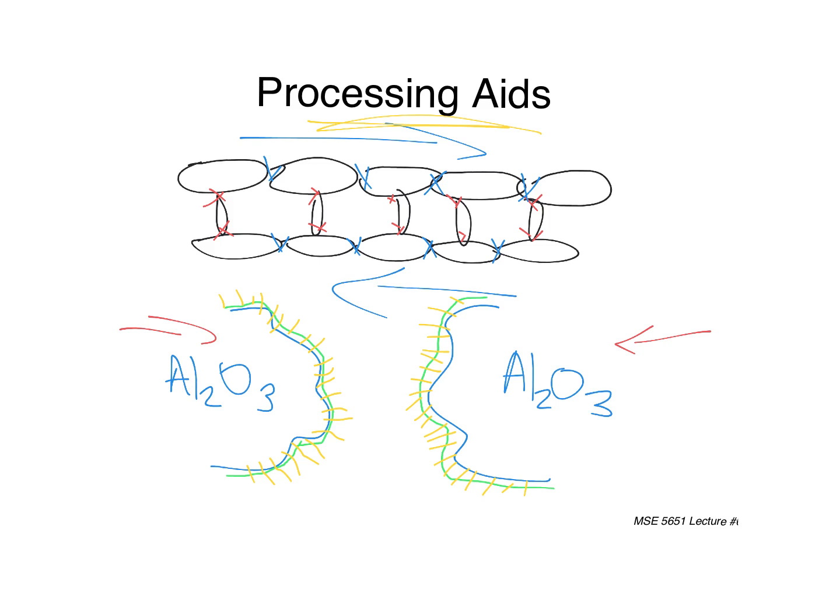Okay, hard agglomeration is the nightmare scenario where the two particle surfaces actually touch each other and they're deep into the energy well, and it takes a lot of mechanical force to pull them out. Soft agglomeration is what we've done here, where we take polymers and we force them to exist in between those two particles, meaning that they can get kind of close together, but not all the way, because the polymer's in the way. At the very least, we have processing aids in the way, and then in these real practical situations, we also have other types of polymers here, whatever constitutes our batch, is also in the way. All right, but we still get some agglomerates, but they're separated by a minimum amount of polymer, and so the forces that hold them together are not that strong.